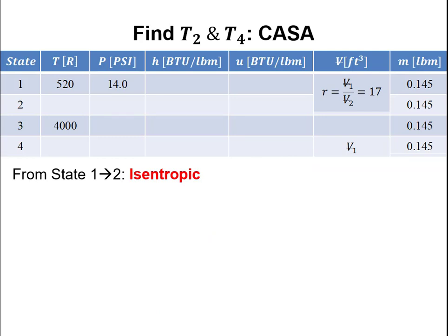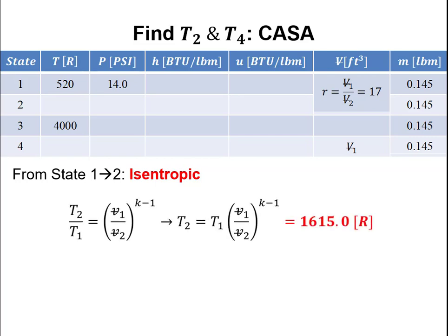So now I've got to fix my states. If I can find my temperatures, then I can solve all these problems because I already have symbolic equations. So the trick to all of these processes that use ideal gases as working fluids is to find the processes that are isentropic. Now state 1 to state 2 happens at constant entropy, so it's isentropic.